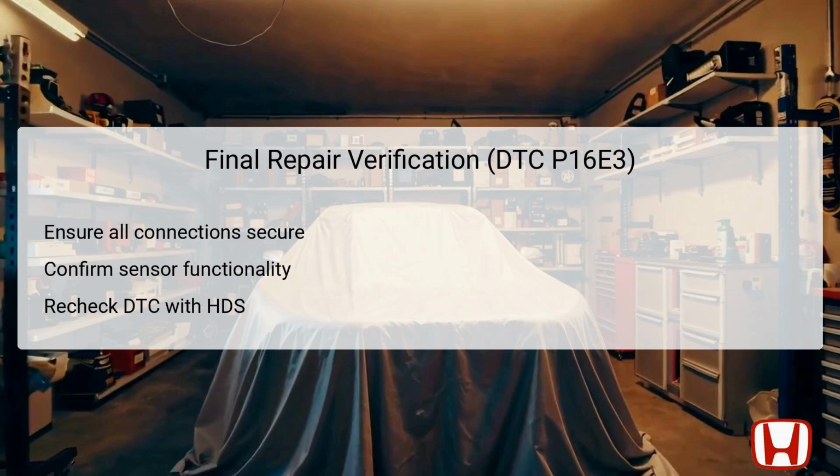First, confirm that all connections, especially those linked to the battery sensor, gauge control module, and any wiring that was repaired, are secure. Also, ensure the sensor itself is operating correctly and that any components involved in the previous steps are functioning without issues. After making these confirmations, utilize the Honda Diagnostic System (HDS) to recheck for any DTCs. The absence of the P16E3 code following these tests is a strong indication that the repairs have resolved the issue, allowing for the vehicle's return to normal operation.